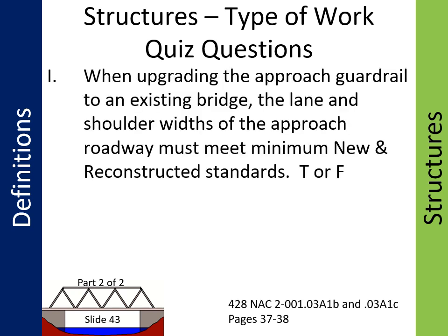Question 1. When upgrading the approach guardrail to an existing bridge, the lane and shoulder widths of the approach roadway must meet minimum new and reconstructed standards. True or false? The answer is false. Upgrading guardrail is a 3R activity. See page 38 of the standards. Therefore, the approach lane width and shoulder width must meet minimum 3R standards.